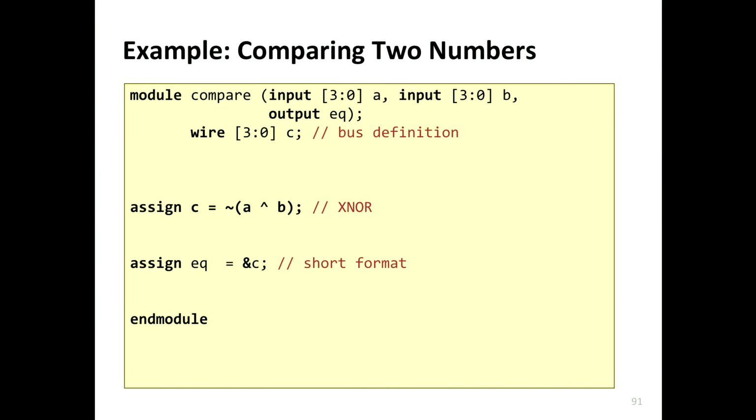Here you have C is assigned to this, and then you invert C. But both of these are going to be executed in parallel. And the system will automatically figure out where to put things, because it's going to be continuously computed. It's not like in C where you pass through one sequence and then the next sequence. Especially in a combinational block, it's going to be parallel execution. But you will see tomorrow how you can instantiate sequential circuits.